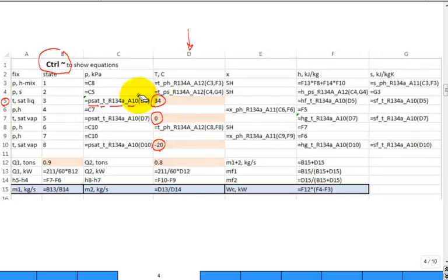So I can see exactly what you're doing in your design. And anybody then can see, and you can share code a lot easier. And so you can see all of the logic. Let's say up here, remember it was pressure and the enthalpy of the mixture that fixed the state? Well, I'm looking for temperature as a function of pressure and enthalpy. And luckily that algorithm was built. And then where is my pressure? In cell C3 and then F3. So it grabs those.